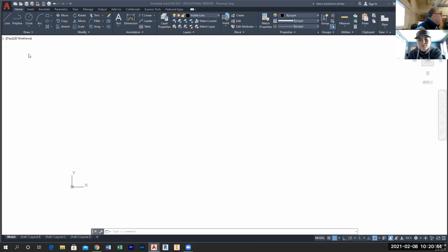Now, the major thing, Cody, you're paying attention, right? The major thing when I'm doing a drawing right now is there's 3 dimensions that we need to be concerned with, and they are what? Do we know? Width, height, and depth. Okay, so the width and length is kind of the same. The depth is in the top view and the right side view. The height is in the front view and the right side view. The width is in the front view and the top view, okay? So those 3 dimensions we're looking at. As I look at this drawing, I'm reading 4.750 for the overall width.